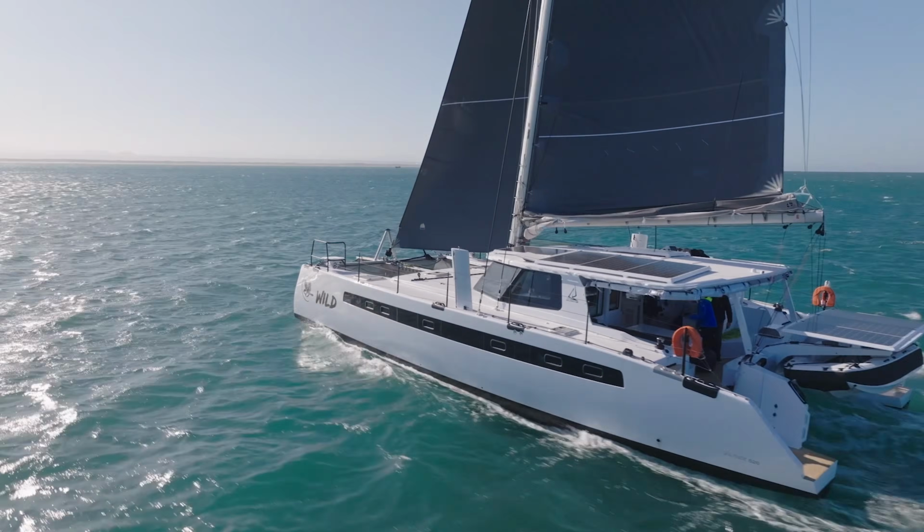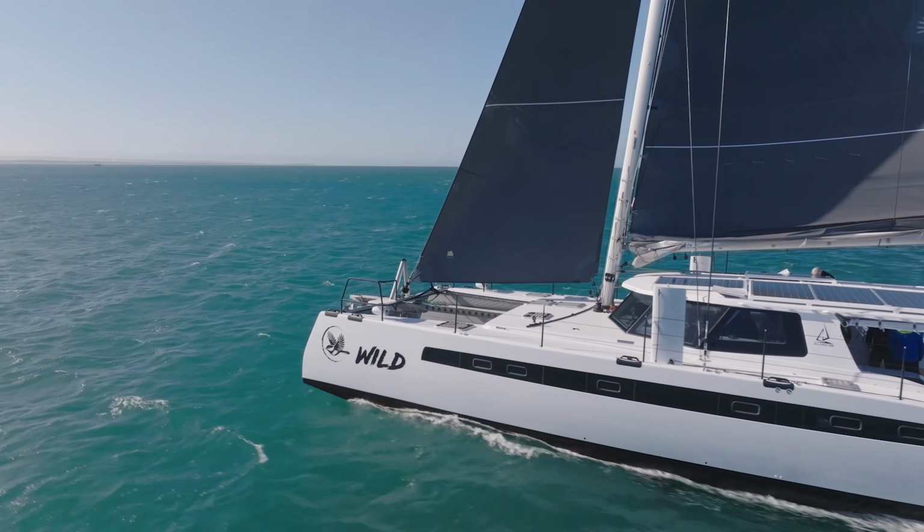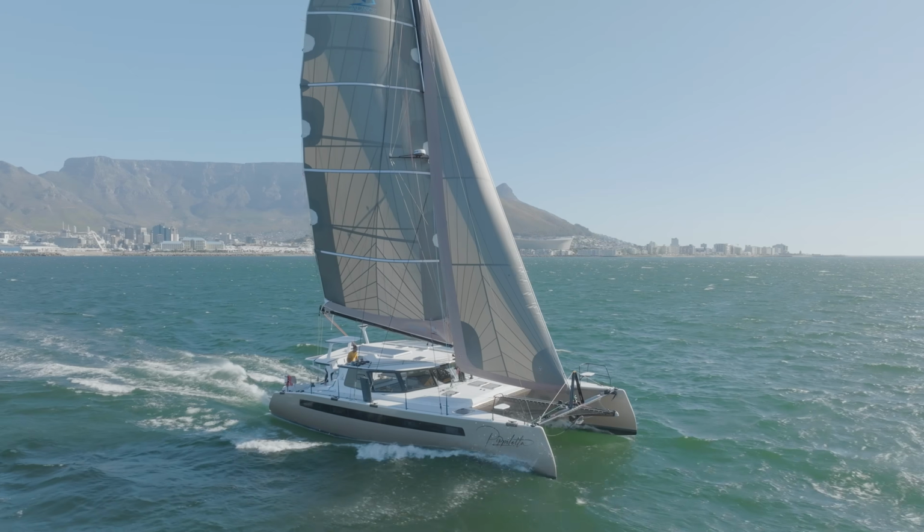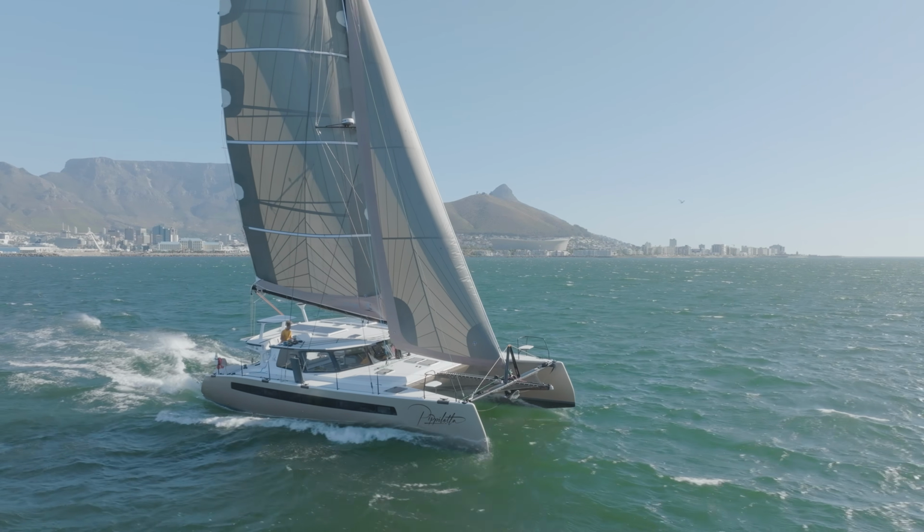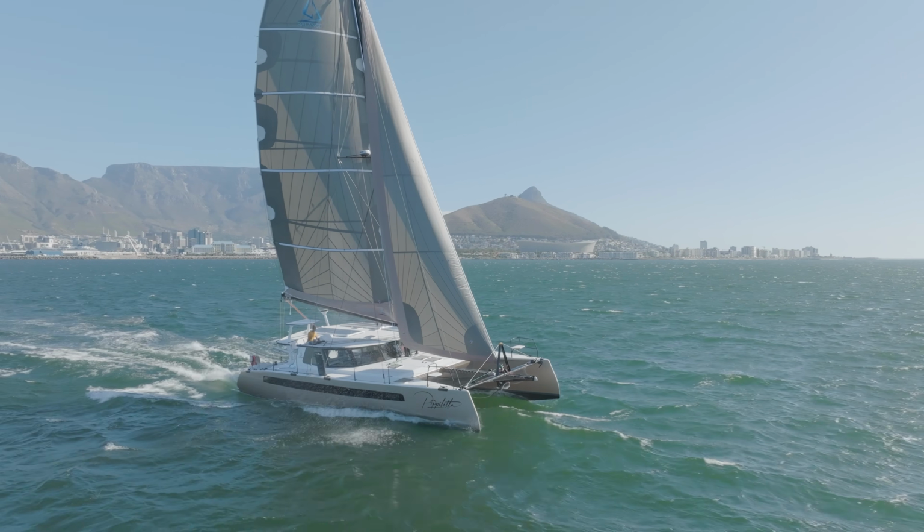Yeah, like Bruce numbers, I don't take them very seriously. There are some social media influencers that say this is super important somehow, but a Bruce number not only doesn't measure the catamaran's beam, but the Bruce number is the same if the catamaran's going backwards or forwards. Or even sideways. So it doesn't take into account the shape of the hulls, the beam of the boat, any of those things which are so important, or the drag of the appendages. So that's why these VPPs are what we turn to.